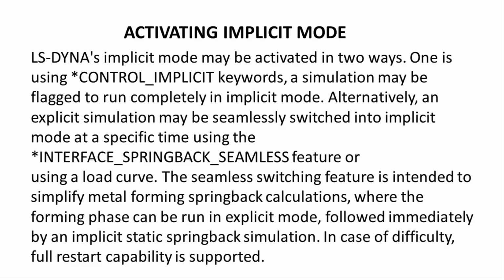LS-DYNA's implicit mode may be activated in two ways. One is using *control_implicit keywords. A simulation may be flagged to run completely in implicit mode. Alternatively, an explicit simulation may be seamlessly switched into implicit mode at a specific time using the *interface_springback_seamless feature or using a load curve.